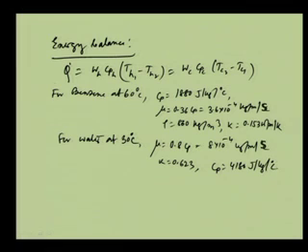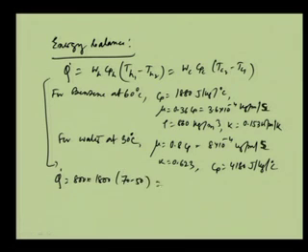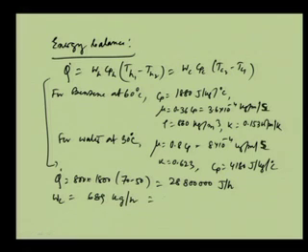And then from the energy balance, we can say that Q dot is equal to 800 into 1800 into 70 minus 50, and that is equal to 2880000 joule per hour. And then Wc we can find out from here. Wc is becoming 689 kg per hour, which is basically 2880000 divided by 4180 into 10. So, that is how we get the W.